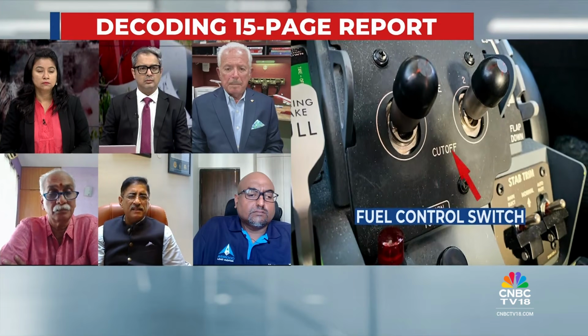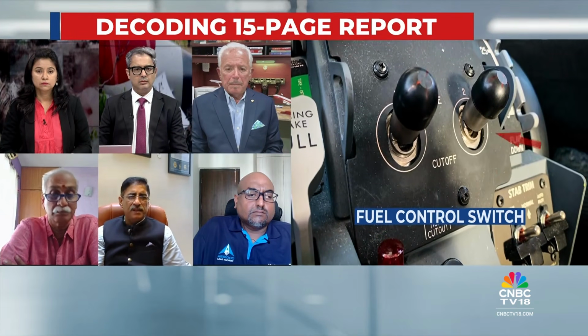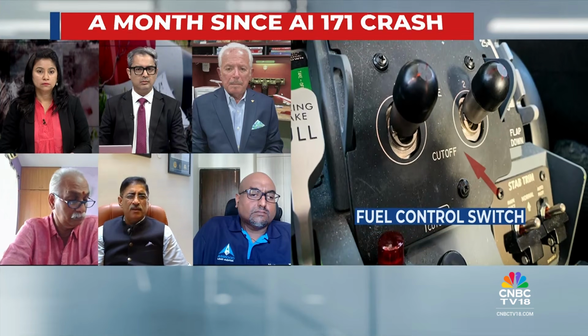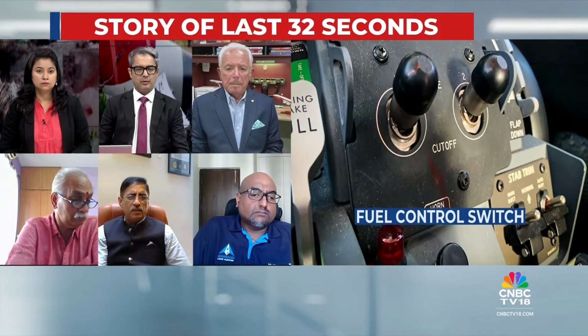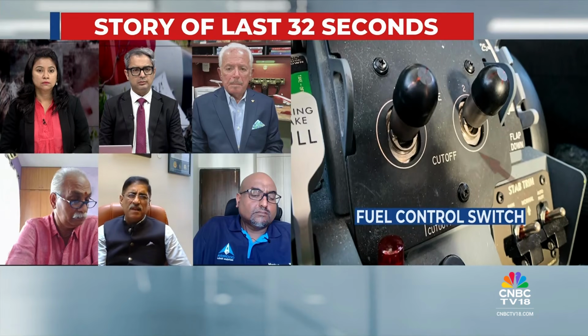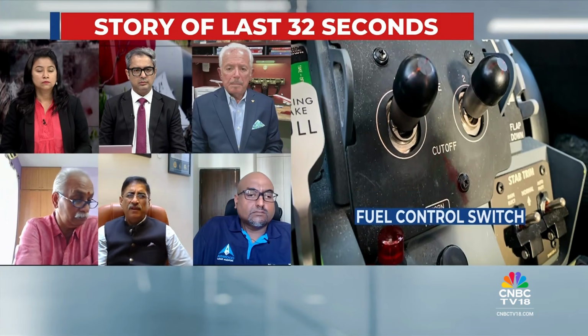Now, coming specifically to your question, there was a similar incident on a 787 in Nippon Airways in Japan in January 2019, when after landing, the 787 Dreamliner pilots operated the thrust reversers, and both the engines got cut off. Now, this is recorded. The aircraft had fortunately landed, it rolled, and thereafter it was towed outside. They did a lot of research. So 2019 onwards, 2018, there's an FAA advisory. Yeah, 2019, on similar, both the engines just cut off in Japanese Nippon Airways.